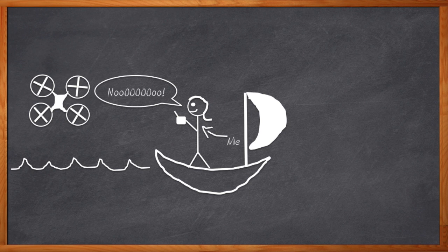So, if you're doing signal integrity analysis and you're using ground as your reference point, you should think about what I just said. Ground may not be as great a reference as you think.